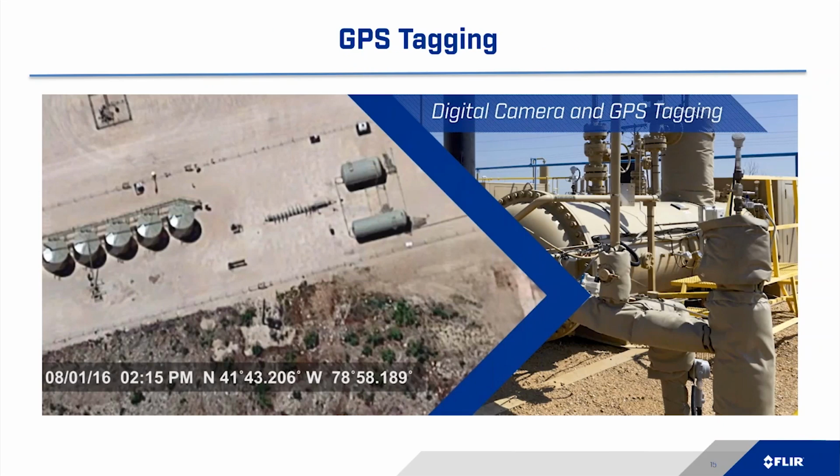And there are also specific requirements for GPS tagging, which is an interesting requirement as well. So any documentation that is taken from the site would need to incorporate a digital camera image. It can be either an infrared image from the FLIR camera or a visible image from the FLIR camera as well that needs to have embedded GPS information into it, which with most all FLIR cameras is a basic feature that's incorporated into the GF series, so not an issue there.